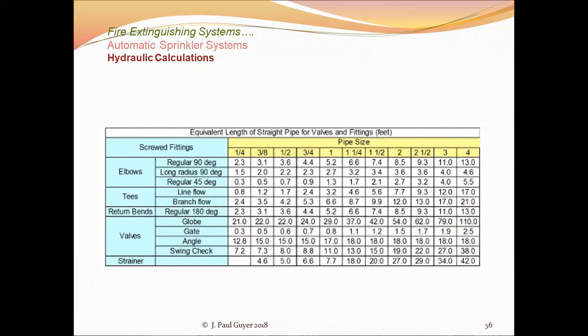And so that tells you the quantity of water that needs to be discharged by that head when it has 20 psi available. So the pressure loss that you can take in your piping system between the point where the water enters the building and where it is discharged from the sprinkler head is 50 minus 20, or 30 psi.